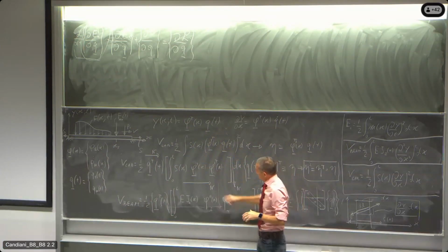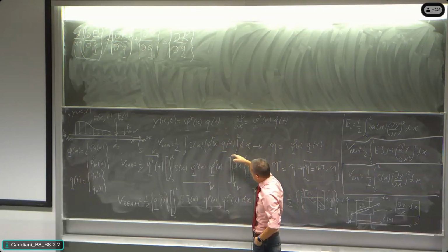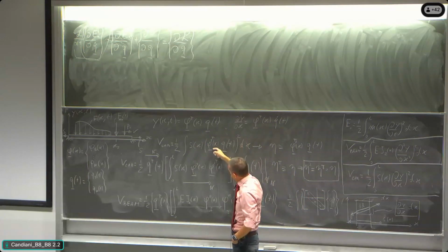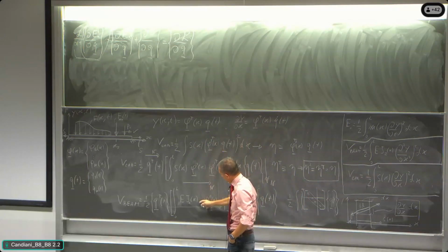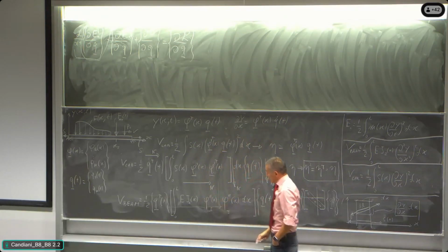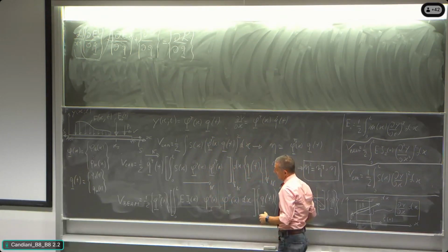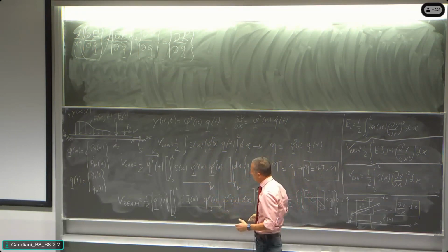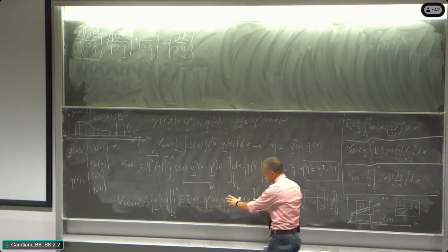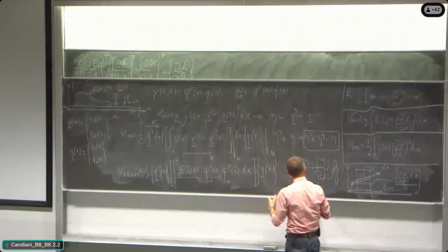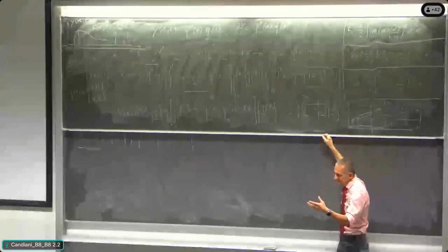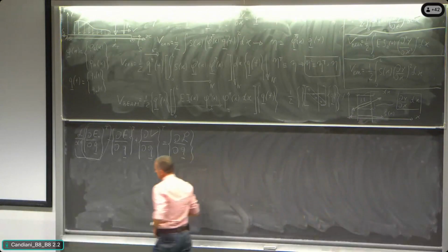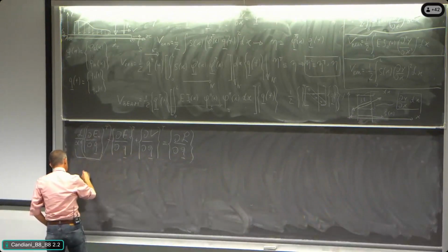The q are the new variables of the problem, functions of time. And we use the zero order to write the kinetic energy that is not here, the first order derivative to write the potential energy of the cable, and the second order derivative to write the potential energy of the beam. We are calculating those numbers, because those are numbers. After having done this integral, we have in our hands the numbers that are representative of the mass matrix and of the stiffness matrix. So everything is becoming numbers, and so we can write directly.